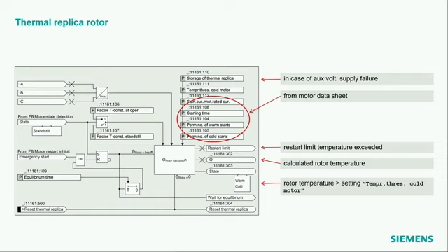I'm a little bit thinking why there is this sign here. It's basically the status of the temperature. There is a setting, and according to the setting, then here I get the information. I have the warm or the cold status of the rotor of the motor. And this is the equilibrium time. So every time I switch off, the motor comes to the standstill.